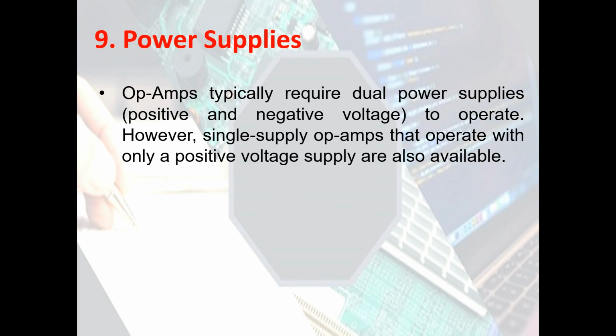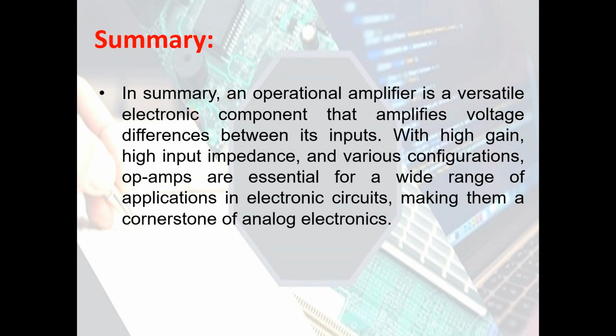Op-amps typically require dual power supplies, positive and negative voltage, to operate. However, single supply op-amps that operate with only a positive voltage supply are also available. In summary, an operational amplifier is a versatile electronic component that amplifies voltage differences between its inputs. With high gain, high input impedance, and various configurations, op-amps are essential for a wide range of applications in electronic circuits, making them a cornerstone of analog electronics.